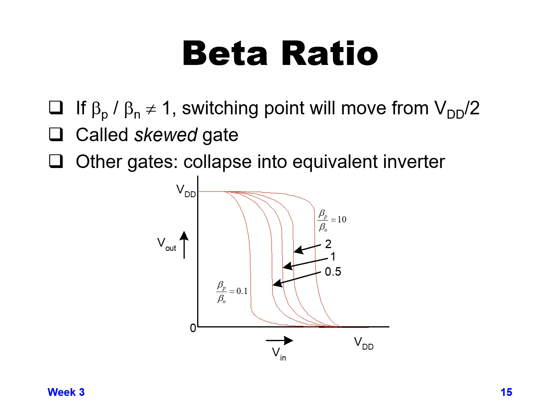And conversely, if your PMOS device gets smaller than your NMOS device, you need a lower voltage to hit that switch point. So in other words, as you change your P to NMOS sizing, you can change the effective place where your logic gate switches between 1 and 0.